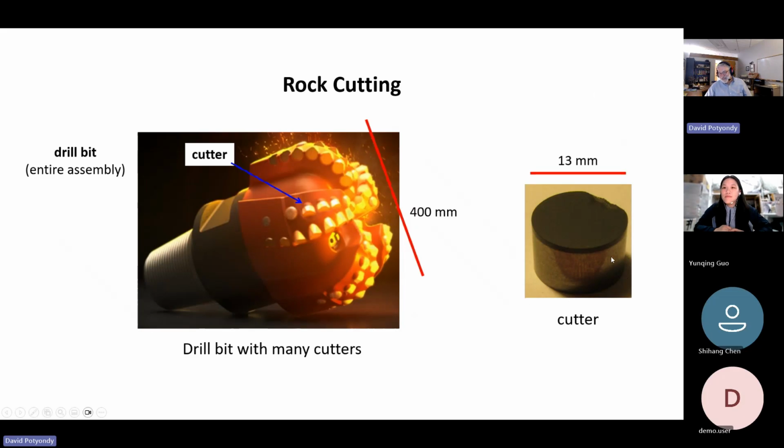This is actually some sort of a metal, and this is actually diamond dust that's been compressed and heated to form this very strong surface that has a very sharp angle. You'd cut your finger if you touched that angle there. They call this polycrystalline diamond compact. This is the part that is pushed against the rock, you can see right here, it's at some angle, and it's forced to move.